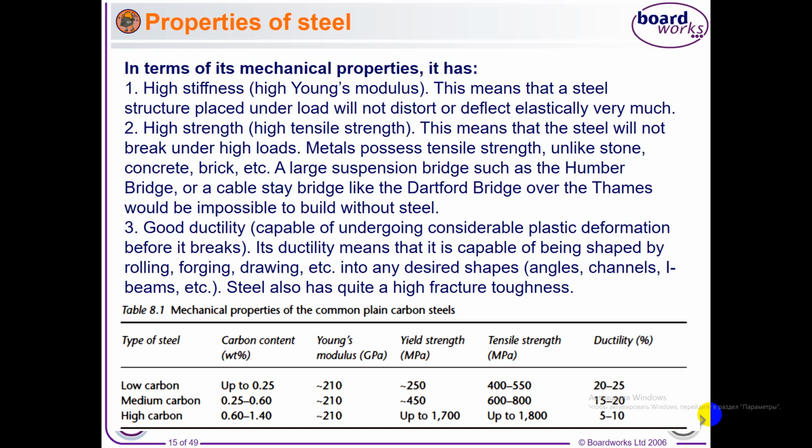Most building fires don't reach temperatures higher than 700-800 degrees, but if part of a steel structure is heated to this temperature, the steel will buckle or collapse under the load it's carrying. And steel also expands when heated, and expansion stresses are also responsible for some of the problems that occur with unprotected steel works in fires.